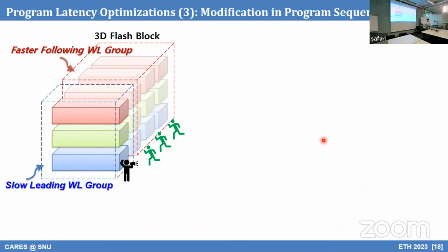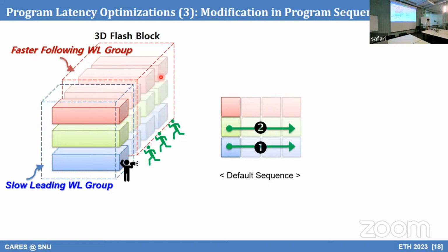Or if you apply this more like burst-style versus regular IO kind of optimization. If you want to make your workload burst-style and you want the best performance on burst write requests, what you can do is this. Traditionally we program each layer at a time. A request comes in, then we write 1, 2, 3, so 3 different layers are programmed.